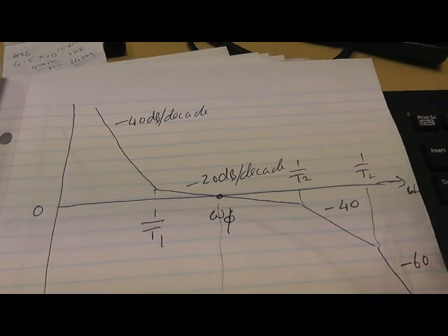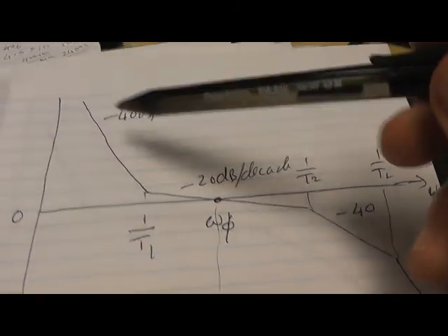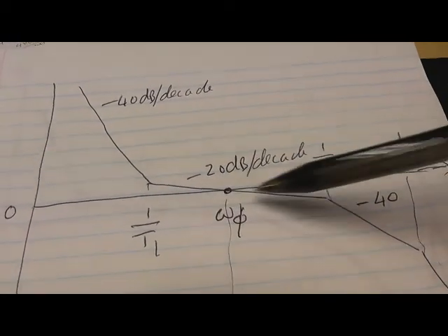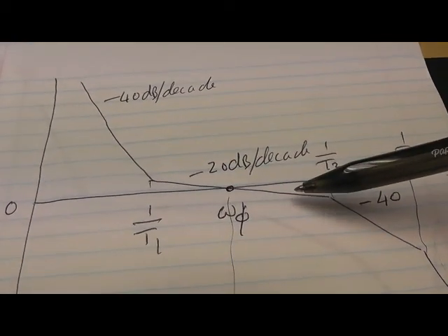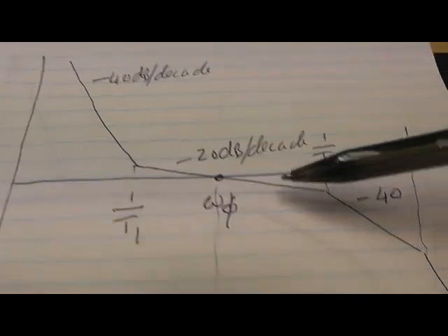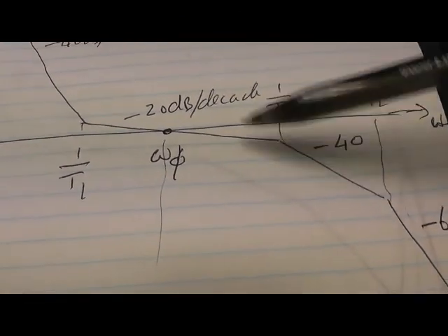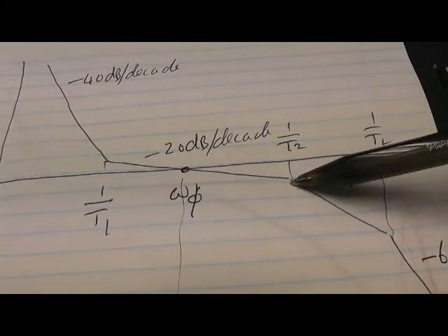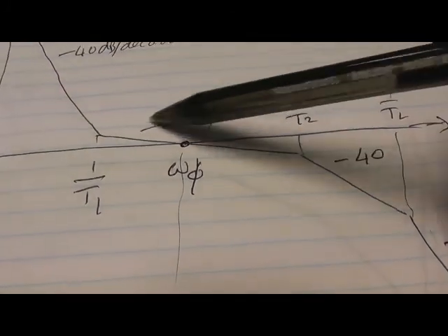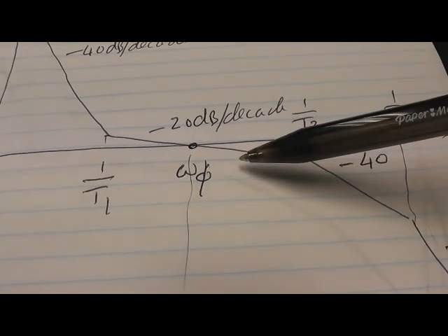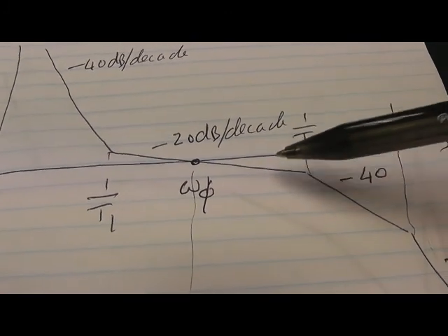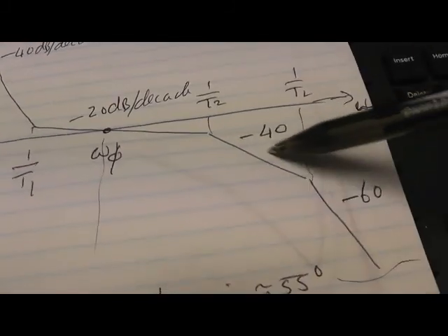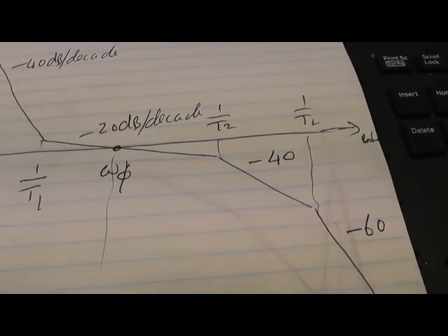So putting in the phase advance, we now get a bode plot that's minus 40 dB per decade, and the phase lead or phase advance now gives us a rise of plus 20 dB per decade, and that takes the slope to minus 20. Minus 40 plus 20 is minus 20, so it goes down through unity gain. And this is a good sign when it goes through unity gain. It's minus 20 dB per decade. It's not a good sign if it goes through minus 40 or minus 60.